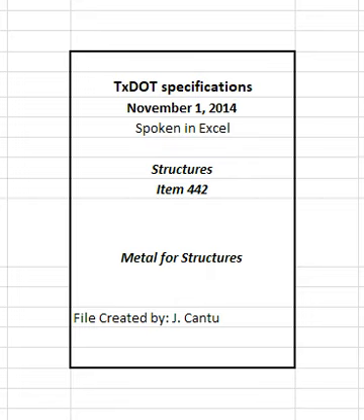2.1.3.3 Fasteners. Provide high-strength bolts that meet ASTM A325 or A490 as shown on the plans. The department may sample high-strength bolts, nuts, and washers for structural connections in accordance with Tex-719-I. Follow the requirements of Item 447, Structural Bolting, for tests, test reports, and supplemental requirements for high-strength bolts, nuts, and washers. Use bolts that meet ASTM A307 and nuts that meet ASTM A563 when ASTM A325 or A490 bolts are not shown on the plans.